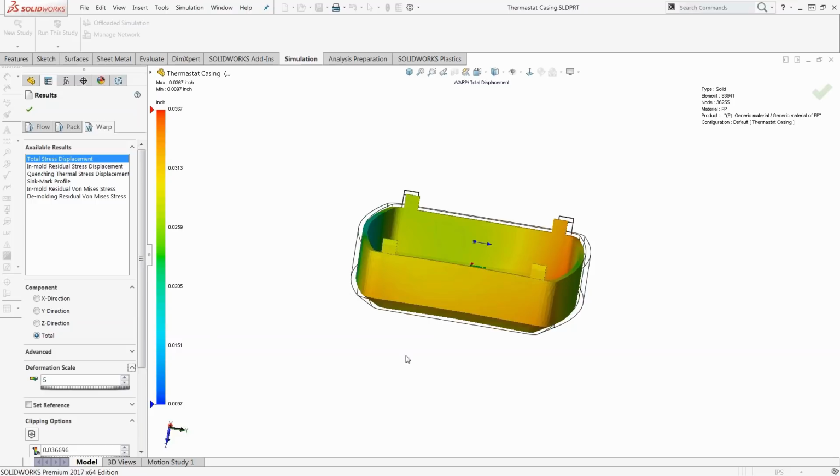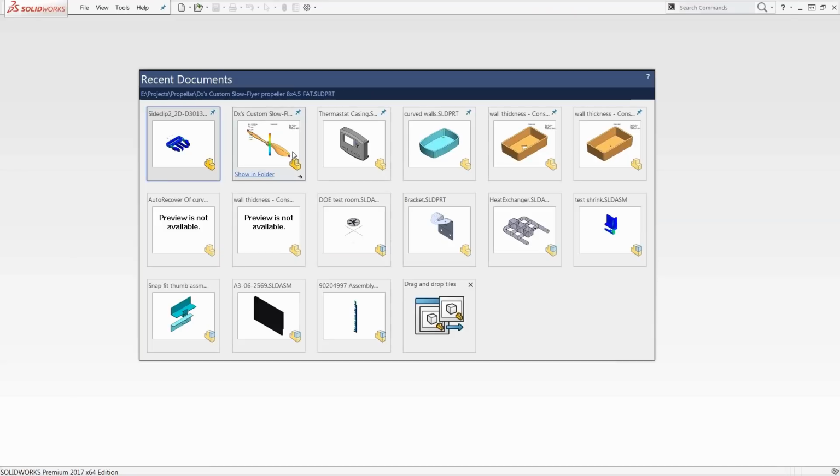But we can see that the warpage is relatively uniform, and that is helped by the location of the gate being central. The uniform shrinkage can be accounted for by having a slightly bigger mold. But let's look at another scenario where the warpage is not uniform.